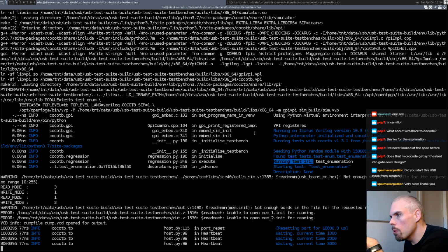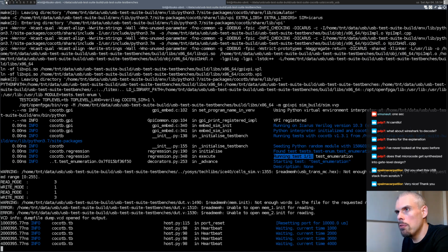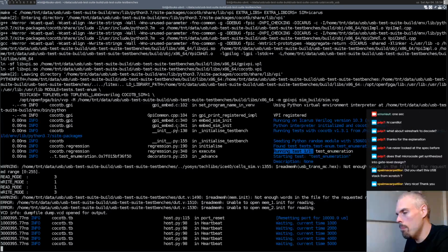And so yeah, that was for the hardware itself, but there is also the, because this core essentially acts like a USB core that you would find on a microcontroller, which means you need a software USB stack that runs the higher level protocol. And currently that's run on the RISC-V soft core.